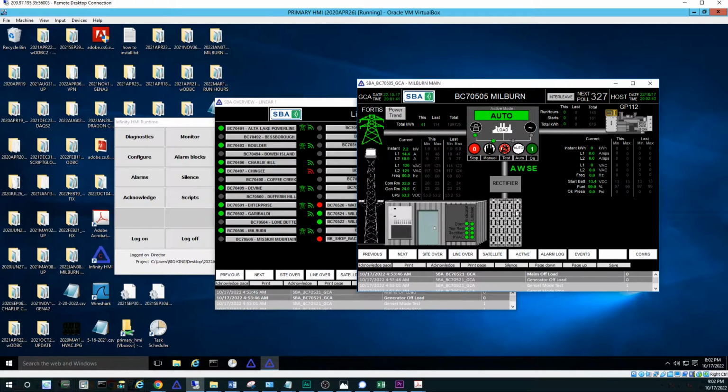Once utility power is restored, this indicator will light again, and a timer will start to ensure the utility power has stabilized. Once the timer completes, the load will be removed from the generator and returned to the utility. This indicator will go dark and this one would illuminate, and the generator would complete its cool-down cycle before going offline. It should be noted that these controllers include a mechanical interlock that prohibits the generator from being able to backfeed the utility line.